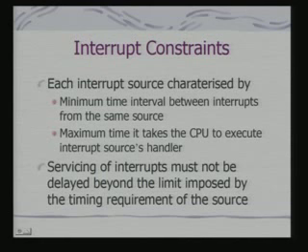And what is interesting to note is that the first instruction in the ISR is not really the instruction of the interrupt source's handler, because I have to figure out the source by checking the flag bit and only then jump to the instructions which are supposed to service the source. And when I am inside an interrupt servicing routine, I am actually disabling the interrupt. So, if there are other interrupts occurring, they have to wait.